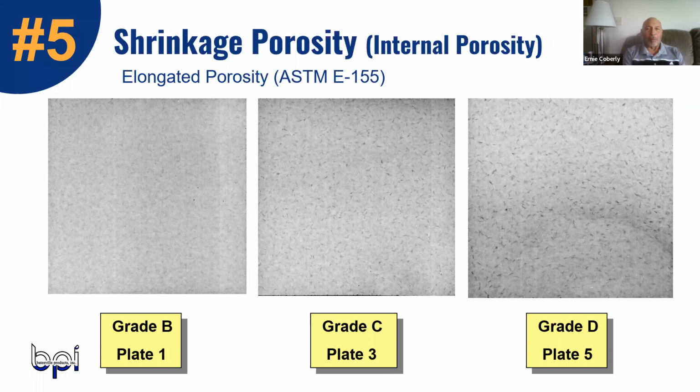in very layman's terms, if you picture a penetrating oil, like WD-40, and add a fluorescent dye to it, it'll carry itself into the parts. You wash the oil off and the penetrant dye remains. And so you can see, through capillary action, it goes into very small porosity. So that's what you see in that slide.